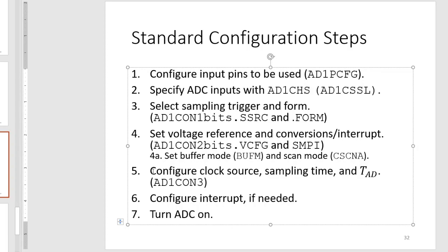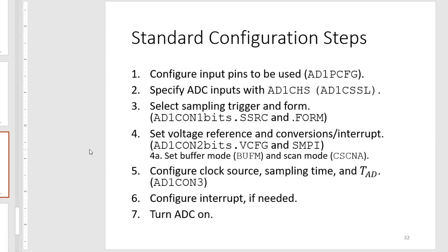Next, you configure your clock source, sampling time, and ADC clock period with AD1CON3. Lastly, you configure your interrupt if you are going to need it, before turning your ADC on.